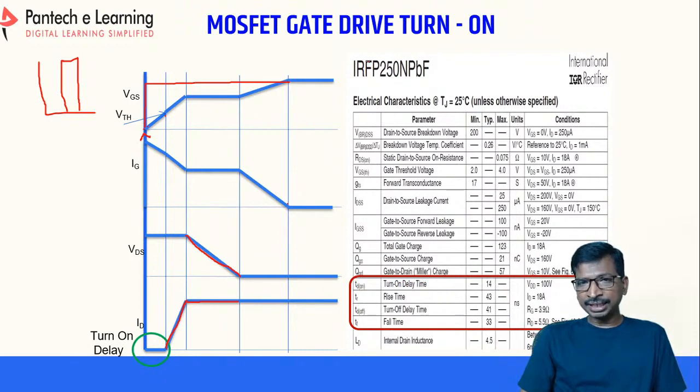In the data sheets, if you take this device IRFP250N, they will mention the turn on delay time, 14 nanoseconds, and then the rise time, which is 43 nanoseconds.